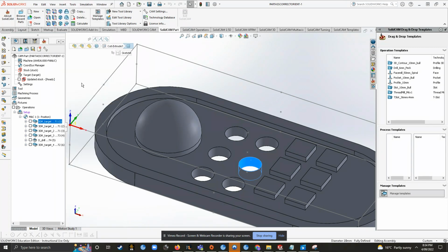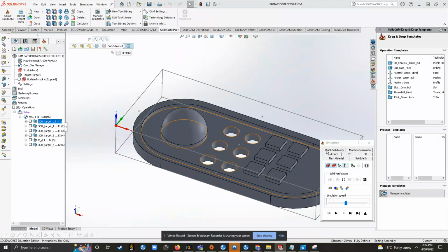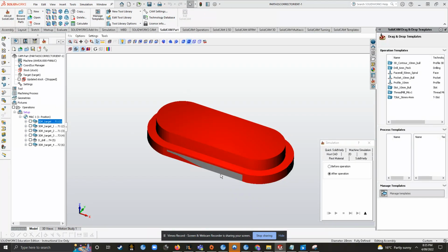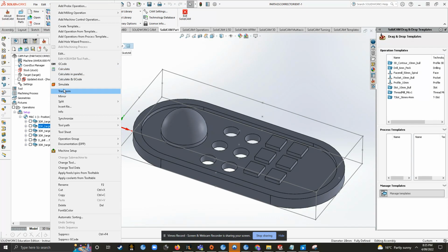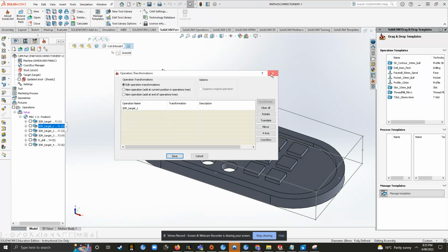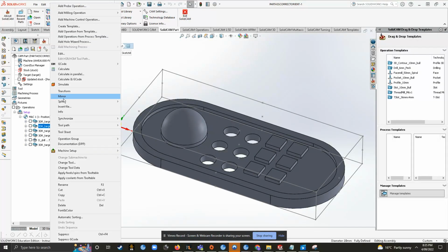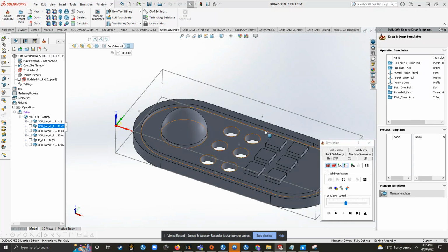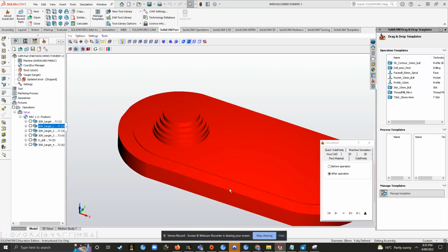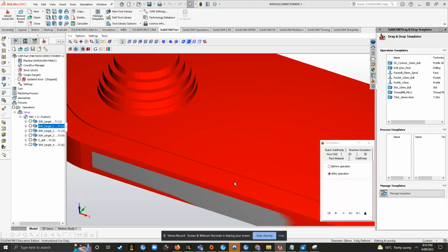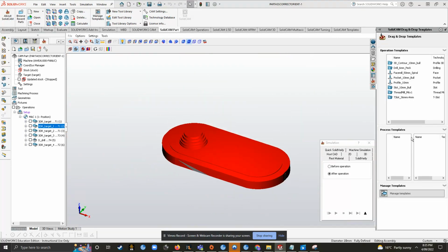So for the first pass, as previously mentioned, just cut out that elliptical profile out of the rectangular stock piece. That was using the bulk 10 mil end mill piece. After that, just cut down to that wall height and just got a very rough cut out of that hemisphere shape.